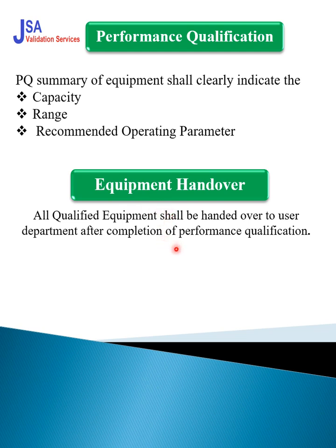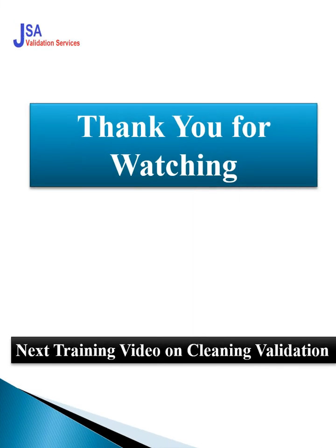That will be your conclusion or recommendation in the summary report. Then you have to generate the equipment handover certificate, and all qualified equipment is to be handed over to the user department after completion of the performance qualification. So this is all about the compressed air system, how you are going to qualify the compressed air system. We have discussed every perspective of the compressed air system.